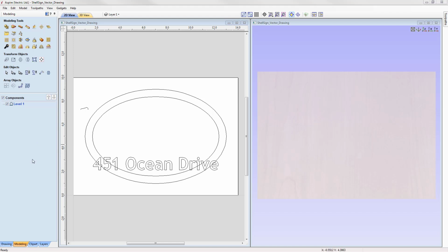Now, as we have no components in our list, we have no components visible in the 3D view, and all we are presented with is the modelling plane. In our component tree, by default we have a level, and if we create components now, they'll be added to this level. The level concept is a smart way for me to organise my components, add multiple levels, change the combined modes of the levels as well as the components within the levels to create the desired composite model.